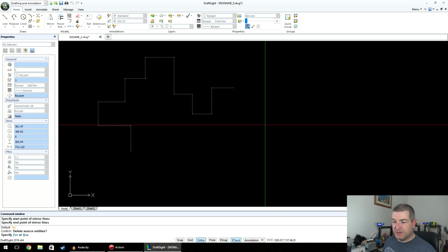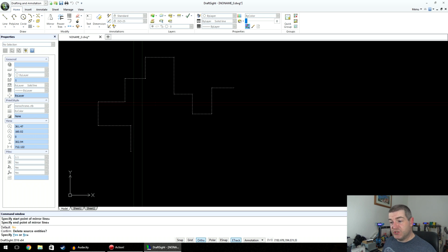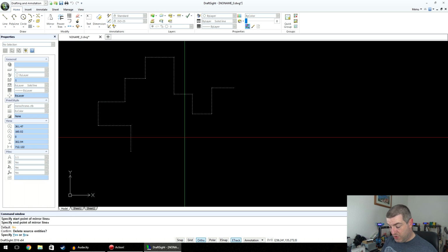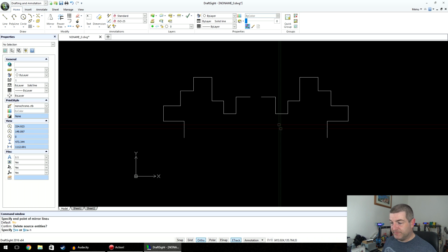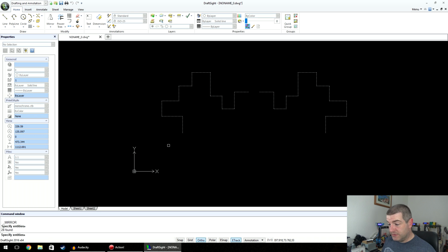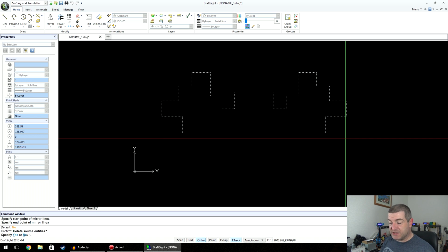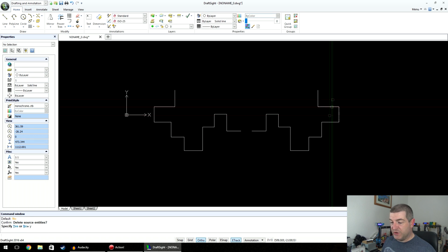Didn't do anything. That's because it's now asking us a question. Do you want to delete the source? If we say no, we get 2. Right, what I'll do is I'll mirror that again. I'll mirror all of it, and I'll mirror it along the bottom here. And this time I'm going to say yes, I want to delete the source, and now we only get 1